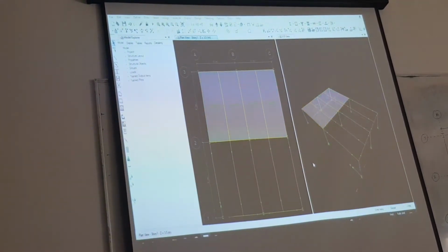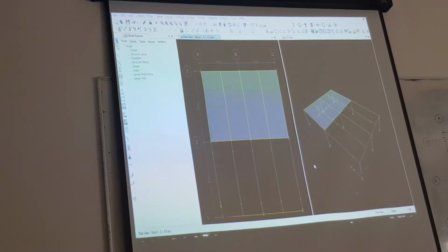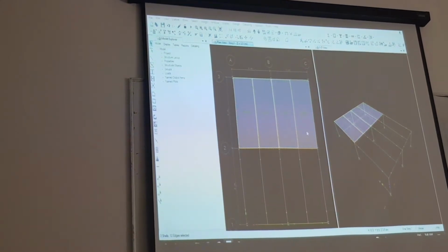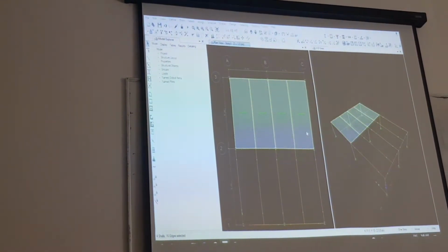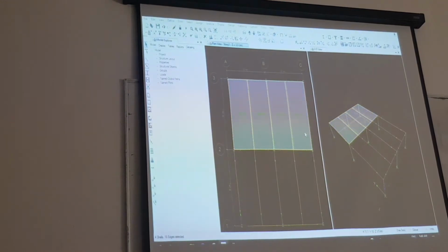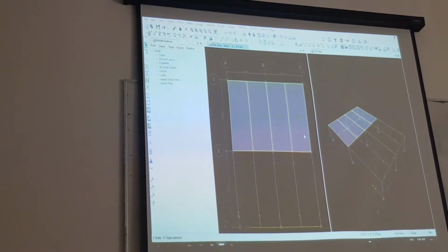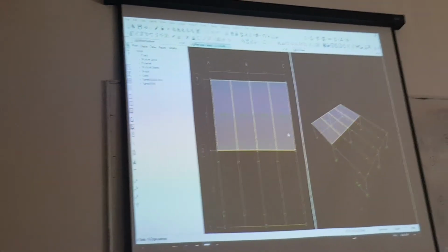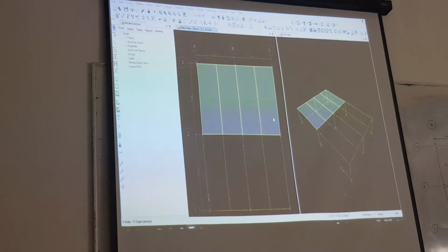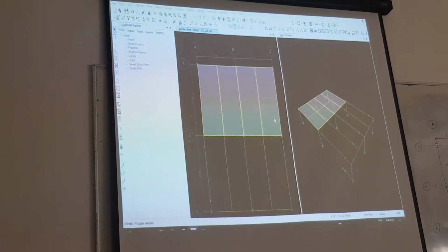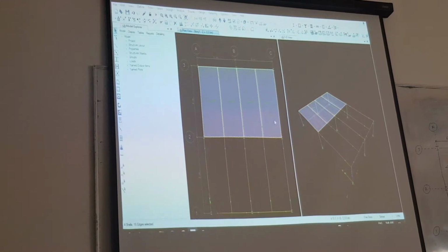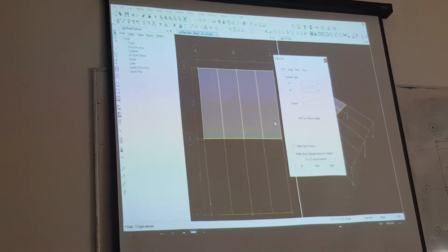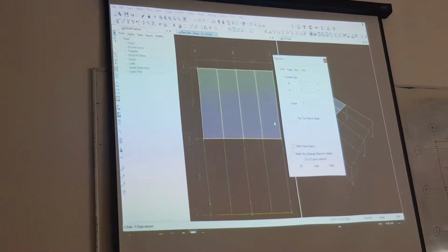Now we are going to do the same procedure, but this time in the y-axis. So let us select all these slabs. Select all the slabs, not beams, slabs. If you select the beams and replicate, it will override the existing beam, which means there are 2 beams at the same time, which will be an error. Okay? So select these 4 slabs, Ctrl plus R, or go to the replicate.